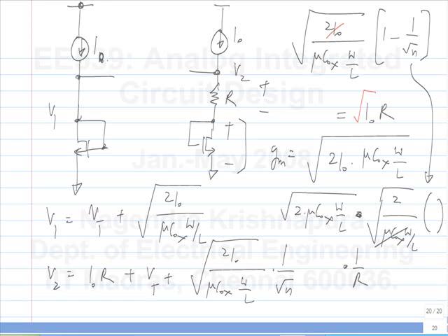Okay. So this goes away. So it is some fixed quantity. I mean, this quantity is not related to any of the physical parameters of the transistors. It's only related to the geometry, right? So it is inversely proportional to R times some scaling factor that you know, because that is one thing that you can adjust in an IC, that is the ratio of geometries. In fact, it's not the geometry itself, but it's the ratio of the geometry of two transistors. Okay, N can be accurately adjusted, as we'll see soon. So here also it so happens that the transconductance of the transistor is inversely proportional to the conductance of some passive component.